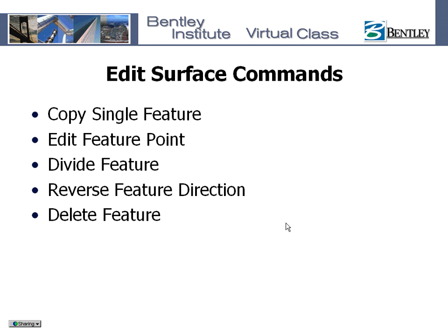Next surface command is delete feature. It removes the feature, it cleans up mistakes, or removes duplicates. This is also an easy one, but I need to stress the importance of feature filter on sorting through large DTMs. It saves a lot of time. This is why well-chosen feature names during importing information into the DTM is very important. By choosing logical naming convention, one can utilize the feature filter to the maximum.